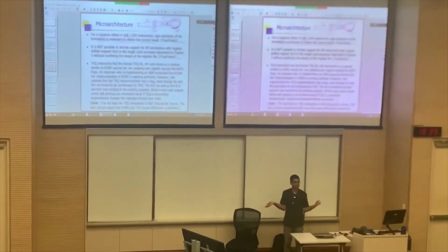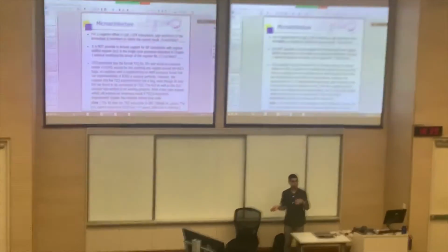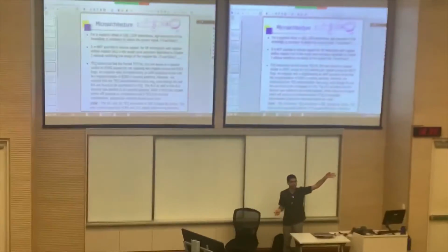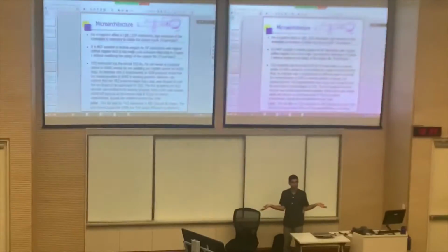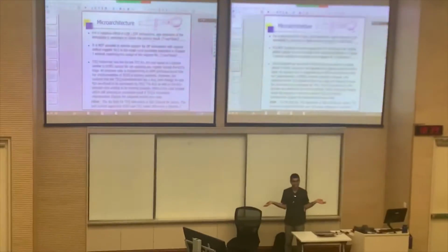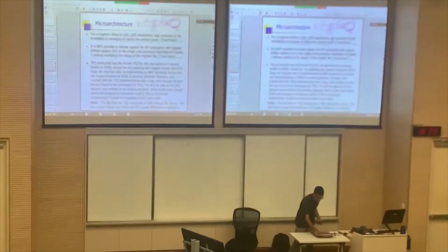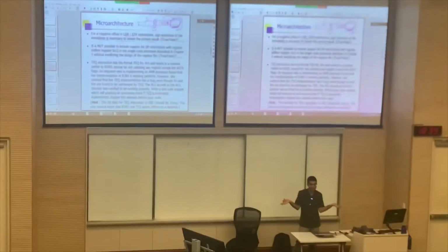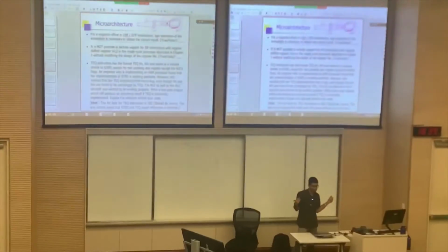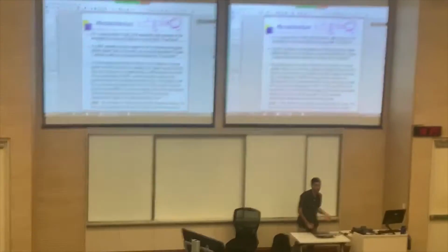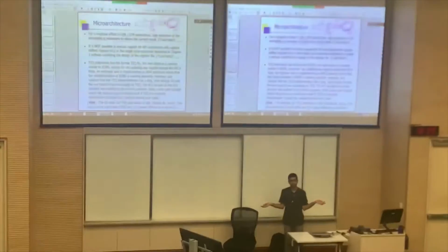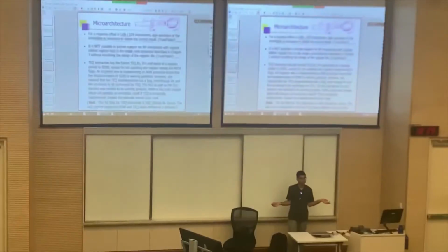What if your most significant bit is 1? Extending it by putting more ones in front will change its meaning, because the number is not signed. So this part is purely magnitude. The magnitude itself is unsigned. The concept of sign comes in only through U bit. So the immediate itself is unsigned, and you wouldn't do sign extension.